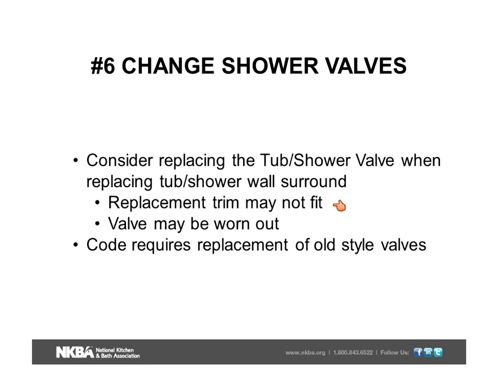Now, when you replace it, keep in mind, if you don't replace it, the valve, a replacement trim, remember I said we want to match our finish. So a replacement trim may not fit it, or the valve may be worn out and you got to replace the thing anyway. And keep in mind that when you get into bathrooms and you start tearing the walls out and doing some major work within that bathroom, if that shower has two handles, when you leave, by code, it may have to have a pressure balance, temperature limiting, or the combination to meet the code.